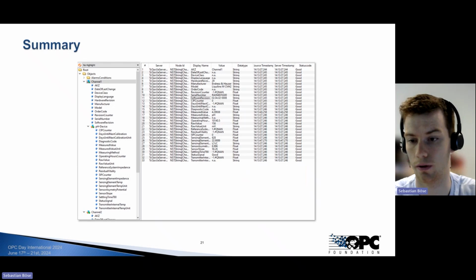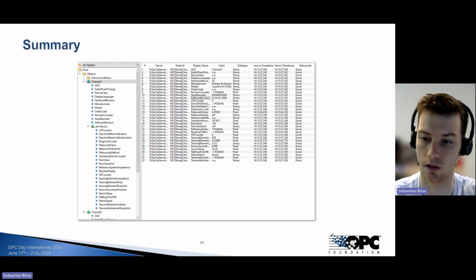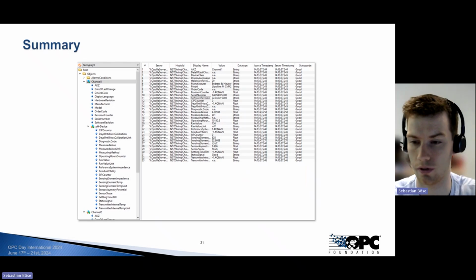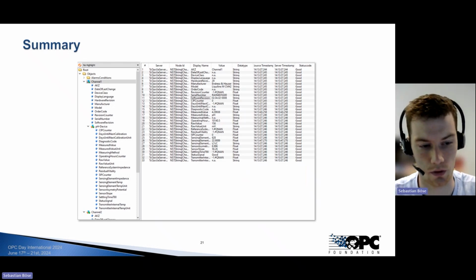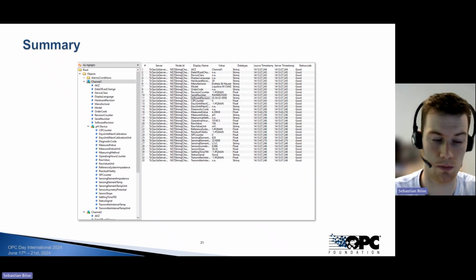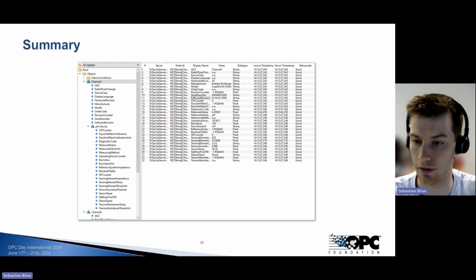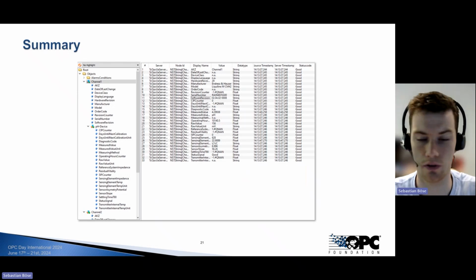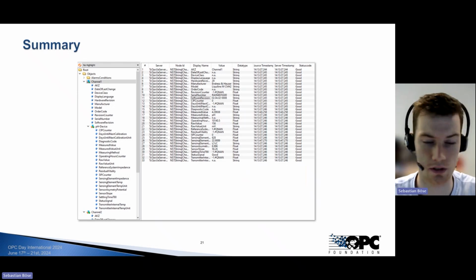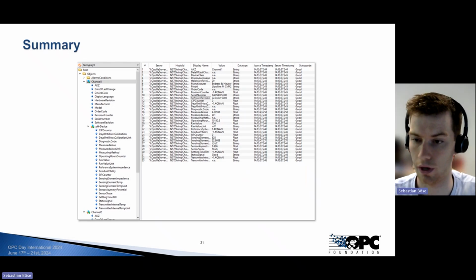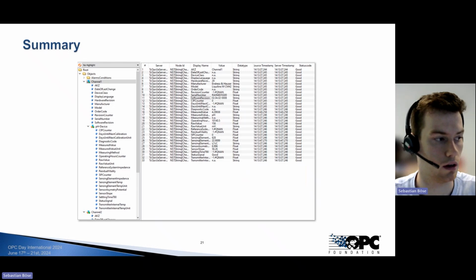So what we do is that we create a node set file, which is then loaded into the OPC UA server. The workflow looks like this: for example, for HART devices, we send in standard commands to get a response from the field device, to know which type of device that is. And whether it's a pH device or an O2 device, the signal or the parameter set is a bit different. So we added the node set in our PLC. We added the whole node set, so it's an XML file at the end. And then we load that into the OPC UA server, which is also running on our controller. And then we have the standardized information model in a really simple way.